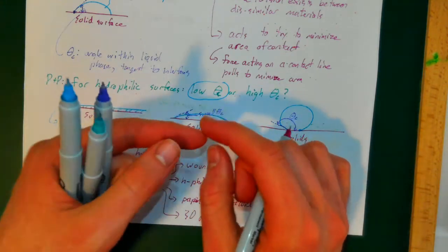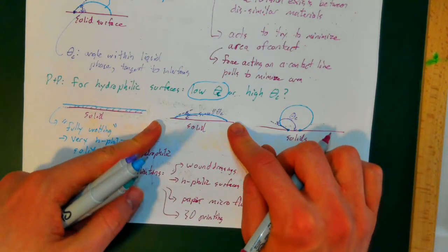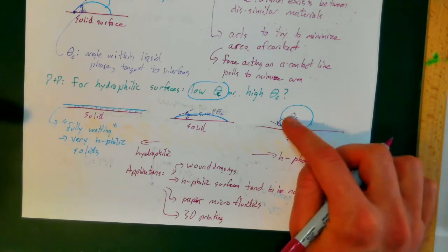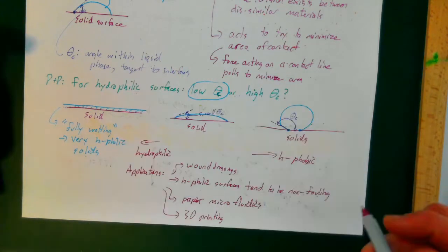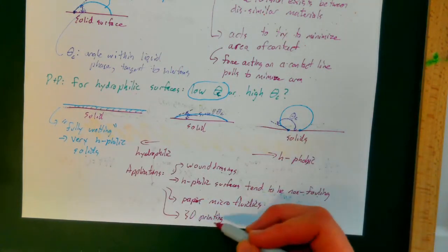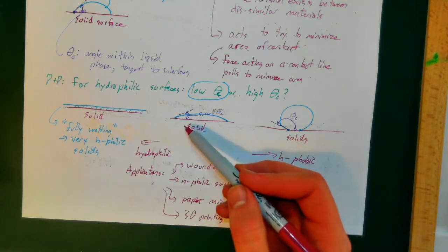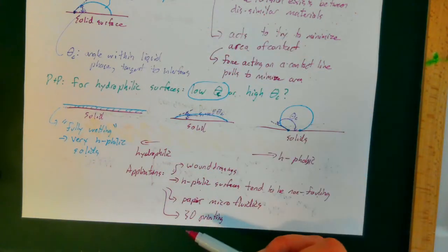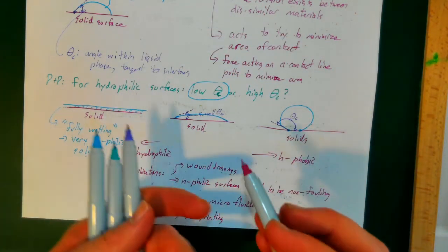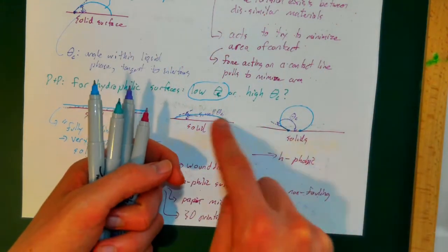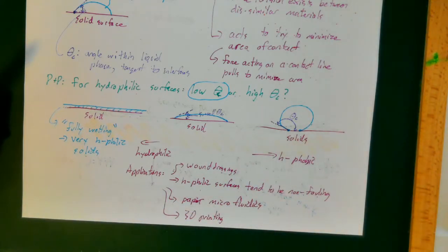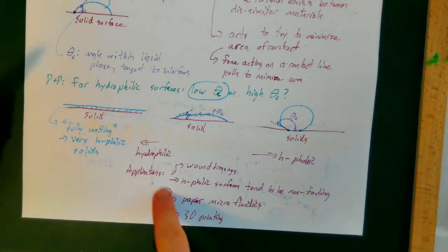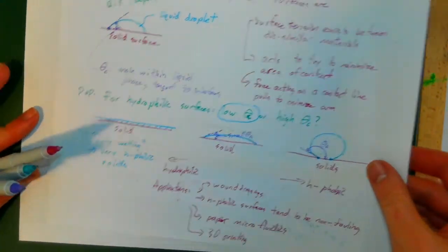Make it too wetting on the surface and it just smears itself out. Make it too hydrophobic and your layers don't stick to one another, because it just beads up on top of the layer instead of sticking to it. So we care a lot about surface tension, contact angles, things like that in terms of 3D printing and being able to maintain accurate feature shapes. This is our bread and butter. These are some of the most important aspects of bioengineering.